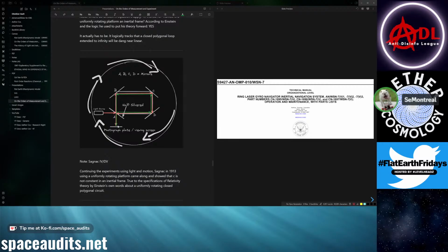Gotcha. So one beam is going one way, the other beam is going the other way, correct? Yep. Fired from the same source. That's what I thought. Okay. But the main thing was if it's on the same platform, so it's on the base of the machine. Yeah, so while this is rotating, it will detect its own rotation. And then in addition to that, if you attach this to an aircraft or something and it's banking or whatever, it will detect that additional velocity.